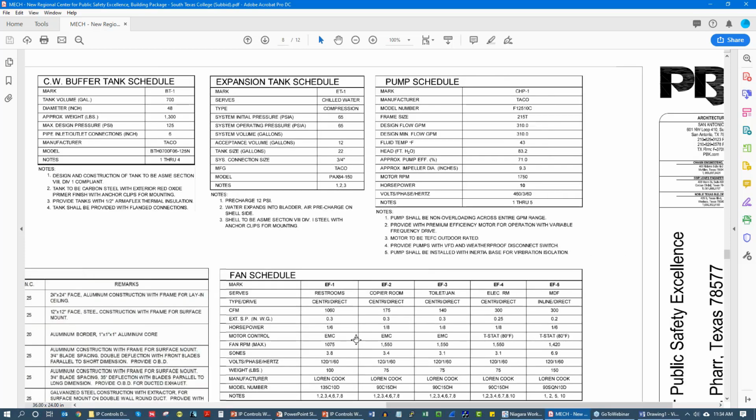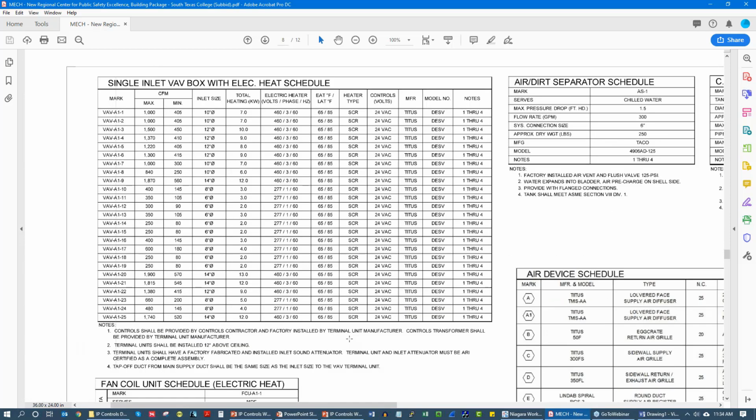This is a school, so it's not really a critical environment. Now, on a hospital or something like that, you may decide that you want to do ring. So look at the spec, understand if the spec is asking for ring or bus. And if it's not clear, you can either go and do an RFI and say, hey, which one would you like me to use? And then you can make your recommendation based on the actual criticality of the site. Or if you don't want to do that, then you can make your own best judgment call.